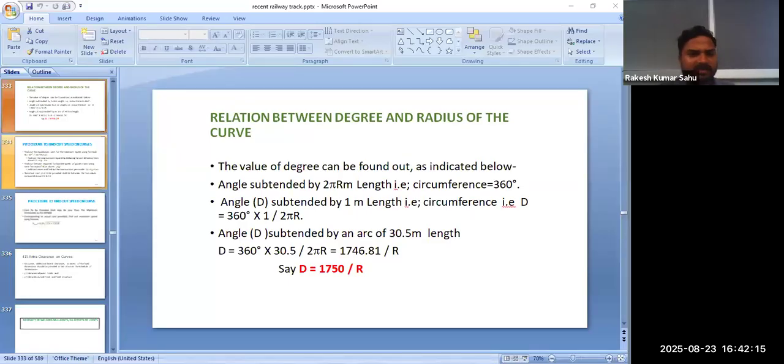Here, these points 1, 2, 3, 4, 5, 6, 7, 8, 9, 10, all these areas were previously fish plated joints. This one is the point zone crossing body, and this one is the switch assembly. Now we welded it continuously to make it CWR, continuous welded rail in the yard. For it, we used WCMS, weldable CMS crossing in the point.